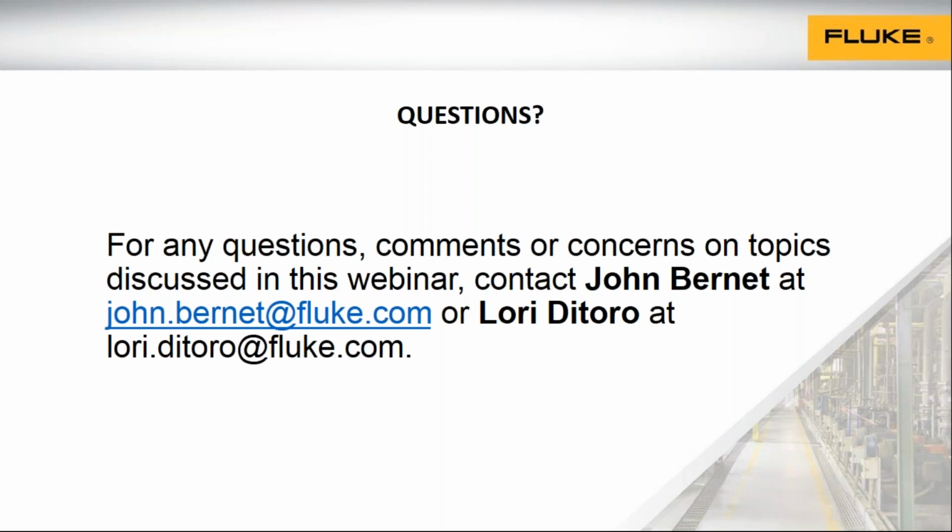That comes in a PDF report, and that PDF can be downloaded and stored in a program like Fluke's eMaint, or you can transfer it by email or anything else. So the answer is, even though we can't trend the vibration numbers, we can store that PDF, look at the PDF from last month, and compare it to see the results over time. I know that's kind of a lengthy way of going around it. So the short answer is no, the 810 can't connect to Fluke Connect because we can't trend the complex spectral data, but you can send a PDF of the diagnostic report to be able to bring up and look at the results later.